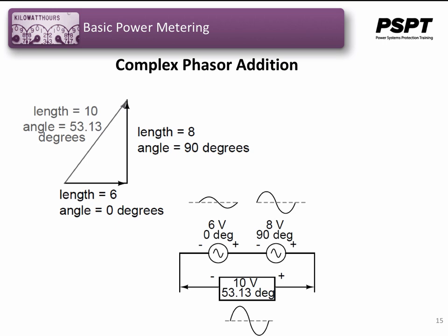Vectors as well as phasors can be moved around a plane as long as their direction and magnitude are maintained. You add two vectors or phasors by placing the tail of one on the head of the other, then connecting the other head and tail, just like in the picture. Compared to DC circuit analysis, this is very strange indeed.